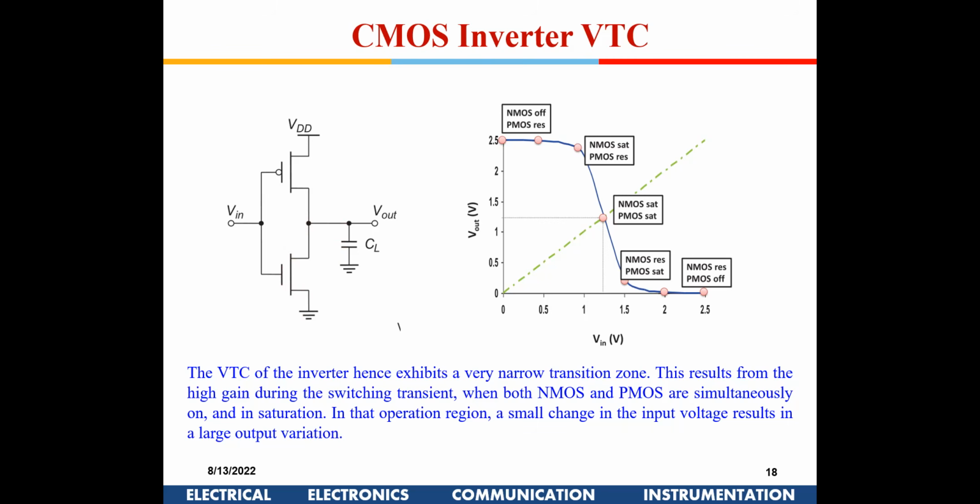Okay. Then, sir, when we have started increasing the Vin, the nMOS current IDS starts flowing through VDD. Correct. Then Vout will start reducing, sir, and so there is a slight slope, sir, in the second phase of the curve from 0.5 to 1. Here. Yeah, Vout will reduce, because this will start pulling the node voltage down. That is the reason.